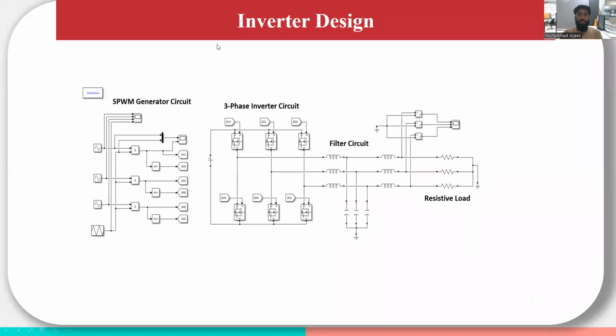Then we designed the inverter in MATLAB Simulink. For that, we made a certain block code for SPWM generation, and then the three-phase inverter design was carried out, and then the filter circuit along with the resistive load was connected, and the outputs were observed.